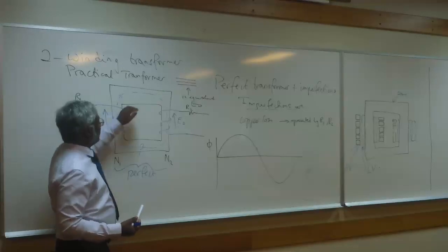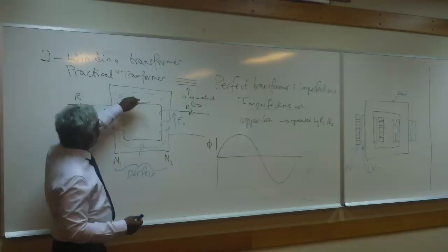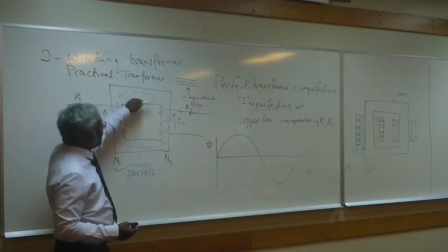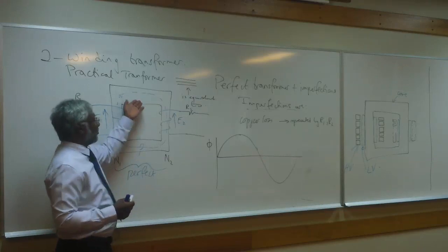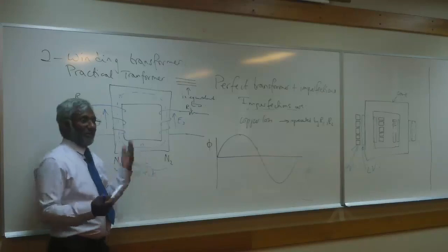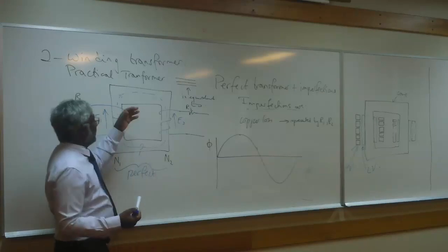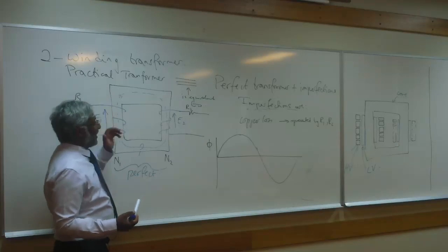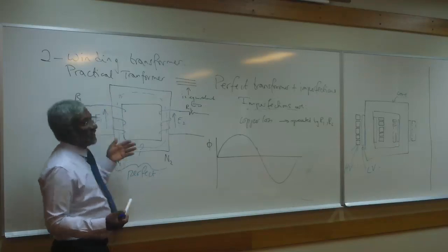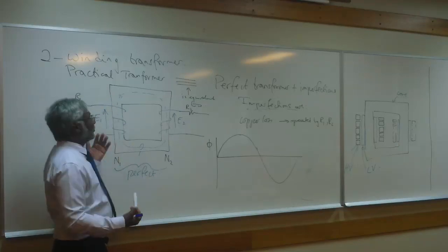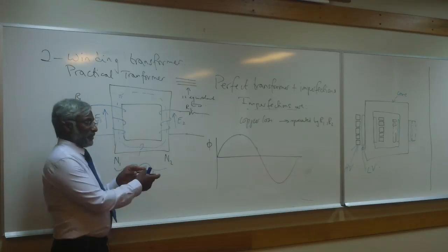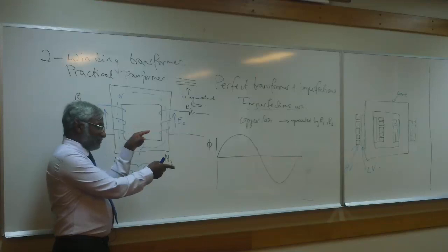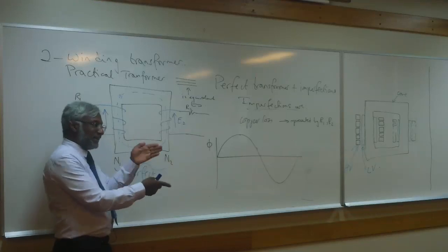So if that core was solid, around those flux lines you would have currents that we call eddy currents. And that would cause the core, in fact, to get hot and maybe even melt. So because of that, we have the so-called eddy current loss, which is a core loss. Of course, we prevent this by laminating the core. This means we break the path of the current by laminating.